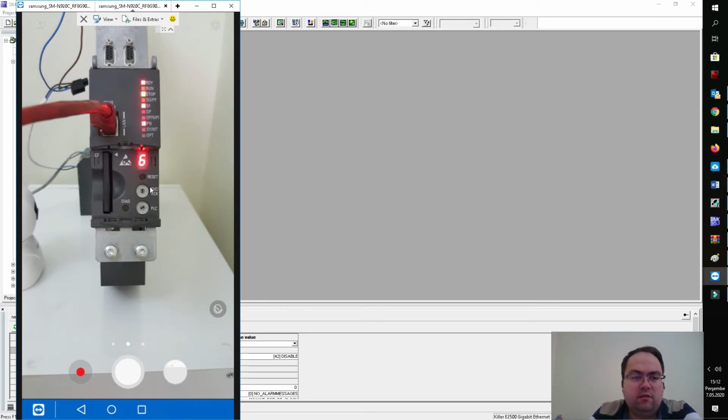In the memory reset case, the PLC memory reset is executed, and the retain variables and the other global variables are initialized. But the hardware configuration is not deleted. So let's try with a factory reset.